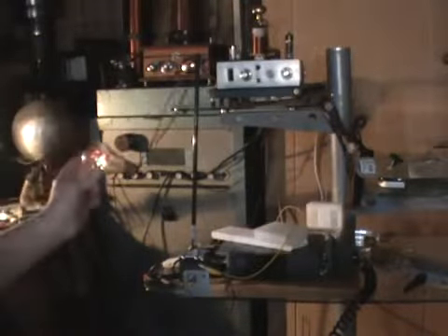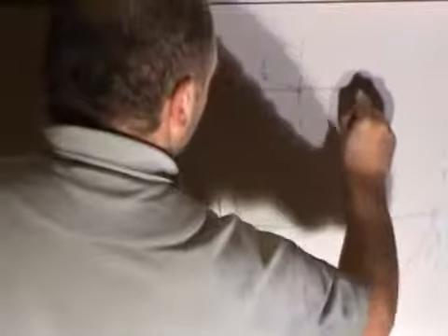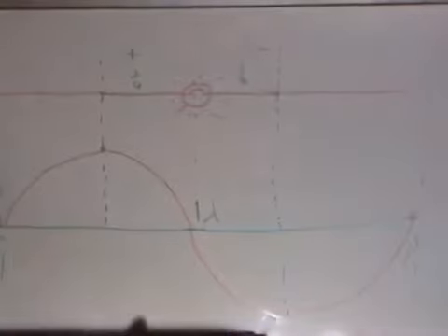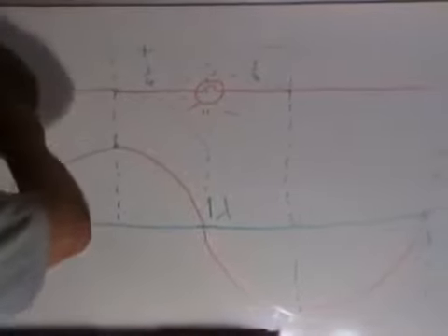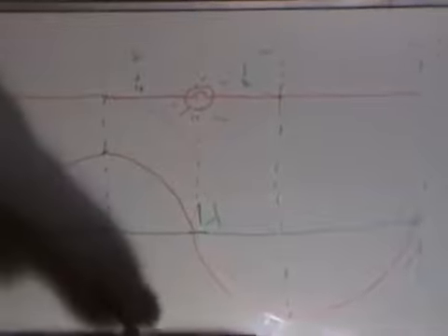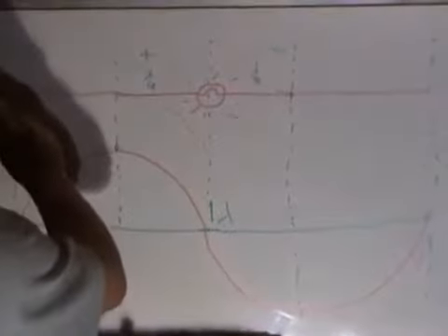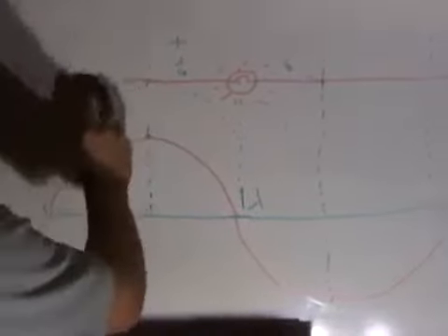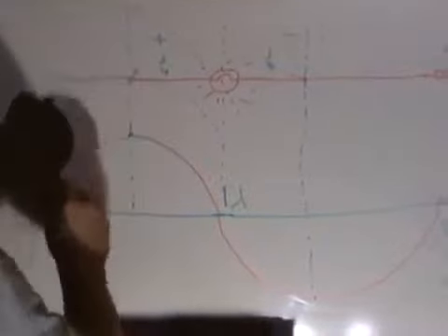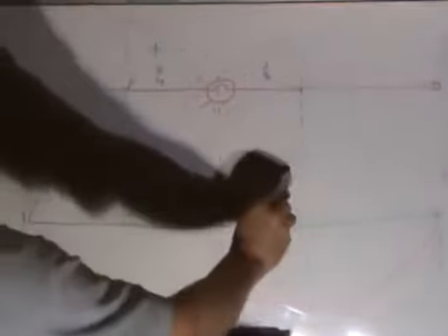It may seem non-intuitive, for the loop antenna appears to be a short circuit, but due to the high frequencies employed, as well as the fact that the length of wire is tuned to a full wavelength, it operates by the same principles electrically as per the previous demonstrations, in that there is a potential difference between two opposing polarities. The tuned antenna peaks at a quarter wave. The loop is actually a folded dipole which causes the light source to illuminate from an equal and opposite potential difference, just like before.